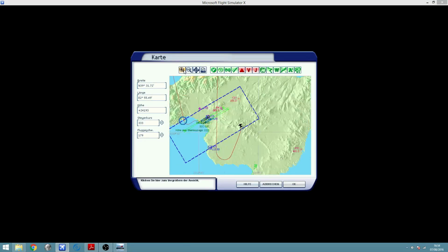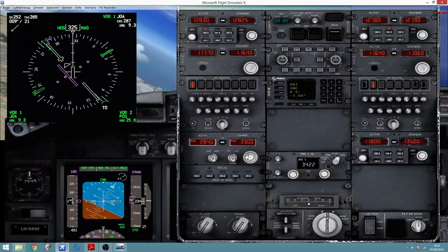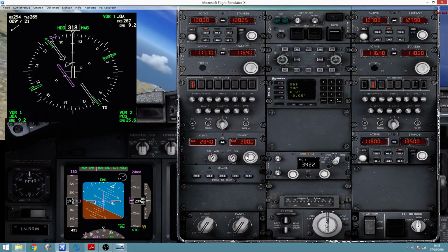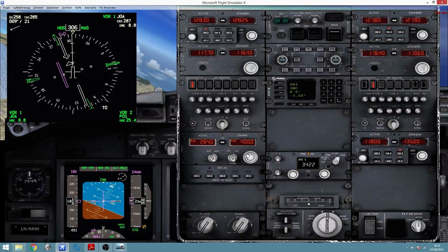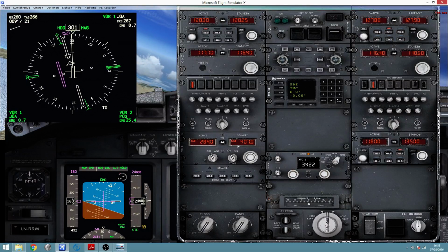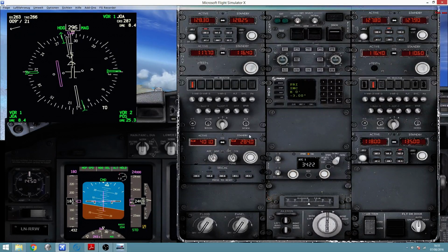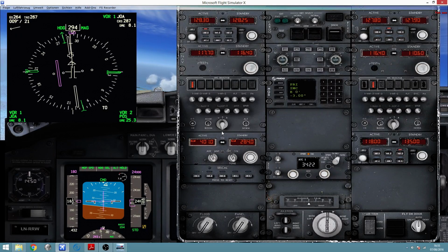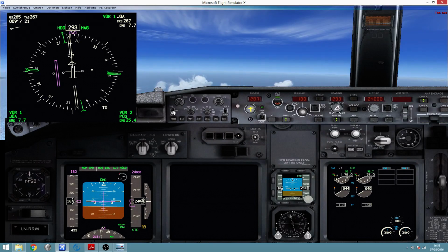Let's look for an NDB station here in the vicinity of Palma. Let's look at this one: Papa Tango Charlie, it's on the frequency 401 kilohertz. So I would have to select here 401 if I wanted to know my position with respect to that NDB. 401, and then I would turn it active, and this is the ADF, the automatic direction finder that we've talked about in class. And then I would have to switch this DME or indication button needle from VOR1 to ADF1.